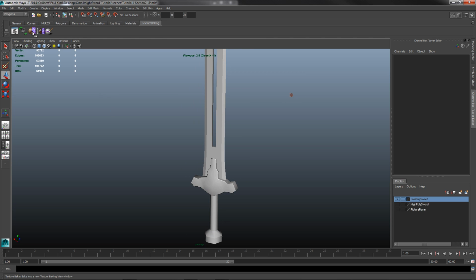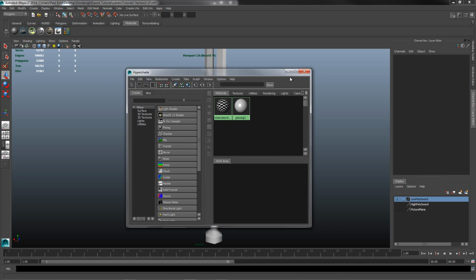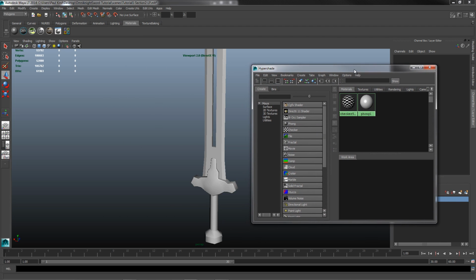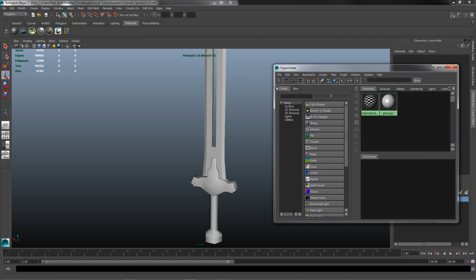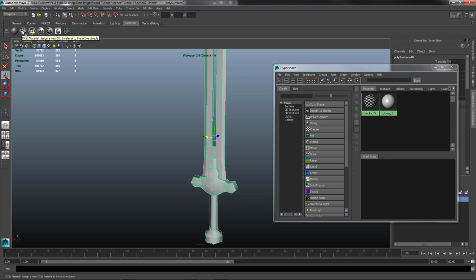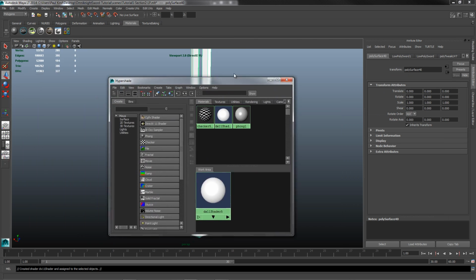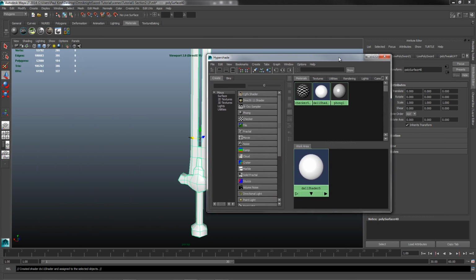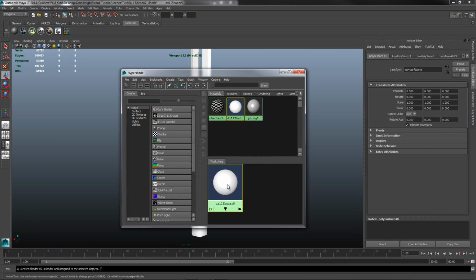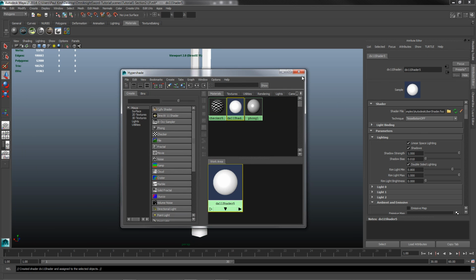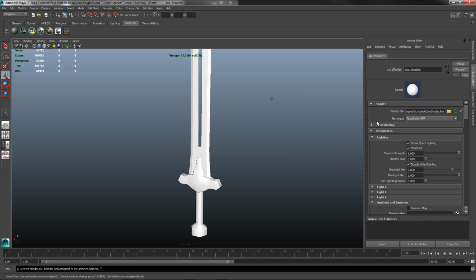And let's go ahead and go into polygons, into materials, and click on the hypershader, okay? So what we're going to do in here now is create a DirectX shader, okay? So select the object and just hit this DX11, okay? So that'll put up this now. What we want to do is start applying these textures, okay? So select your DX11 shader, and let's start managing the maps.